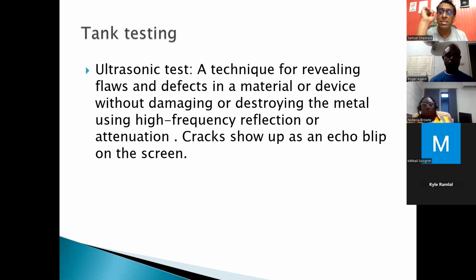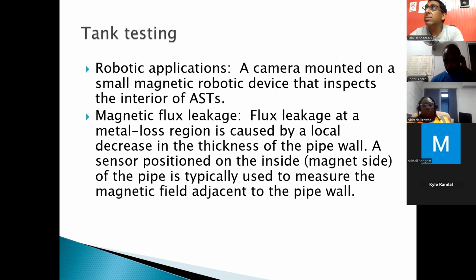Ultrasonic test: a technique for revealing flaws and defects in a material or device without damaging or destroying the metal. Using high frequency reflection or attenuation, cracks show up as an echo blip on the screen. Robotic application to test a tank: a camera mounted in a small magnetic robotic device. A drone could inspect the interior of a tank.